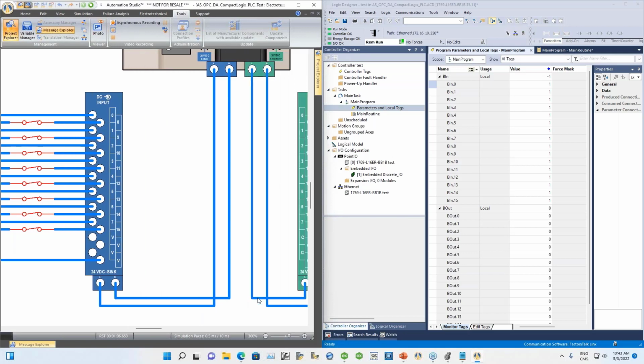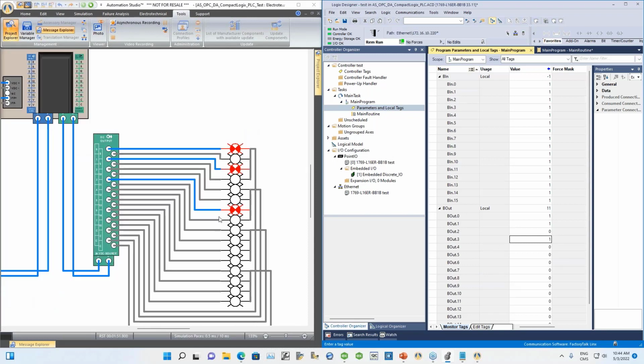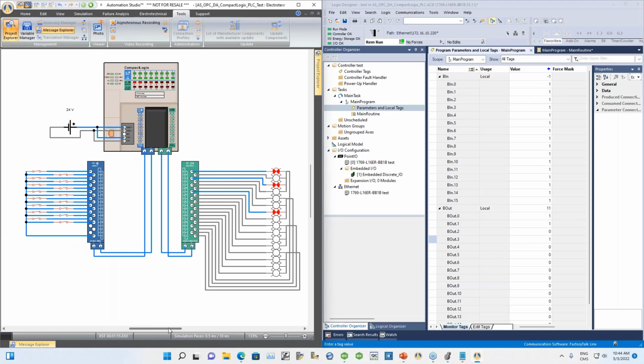Now, assume there is a logic running in the PLC, and the logic says that I want to activate output 0. If the PLC decides that this value is 1, enter. You see it receives it, and I'm getting a light that turns on. It's skipping because this is actually how the pinout is on the card. This shows you that my template, which is already pre-configured, is in communication with my PLC.